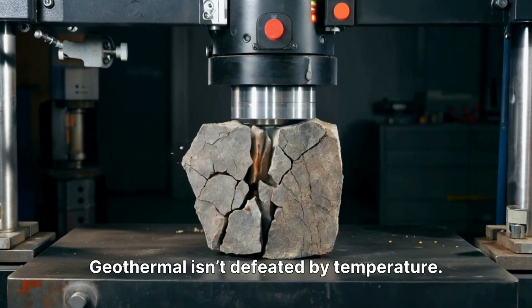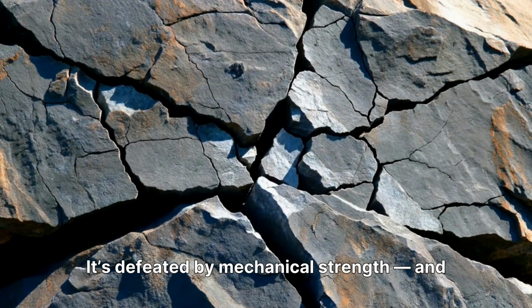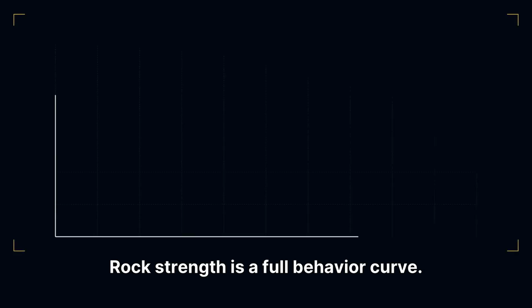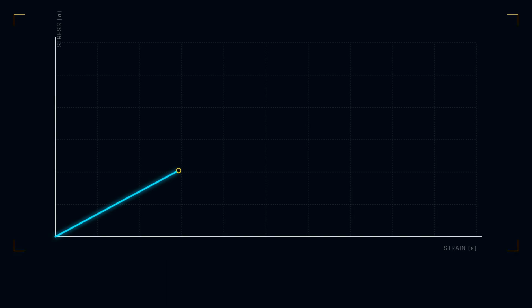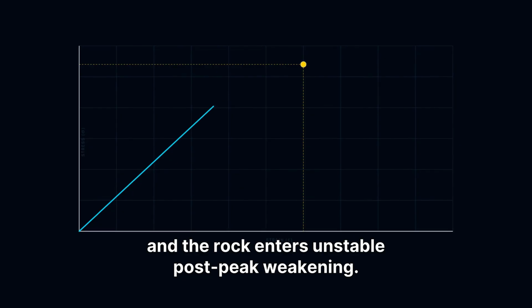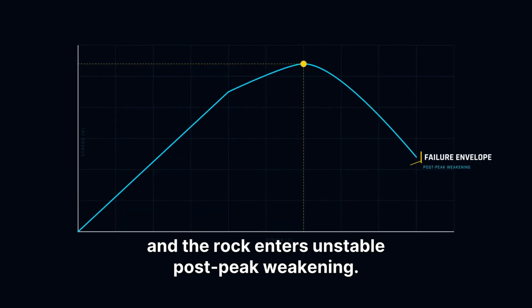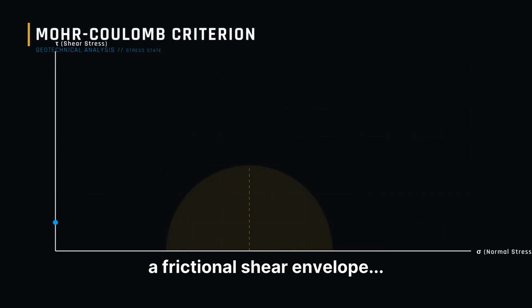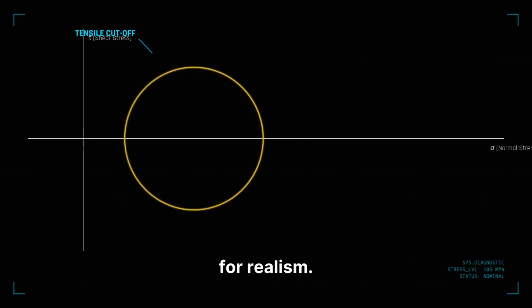Geothermal isn't defeated by temperature, it's defeated by mechanical strength, and the fractures you can't fully control. Rock strength is a full behavior curve. Before failure, microcracks accumulate, then the system reaches a peak, and the rock enters unstable post-peak weakening. The classical engineering view is more Coulomb, a frictional shear envelope, usually combined with a tensile cutoff, for realism.